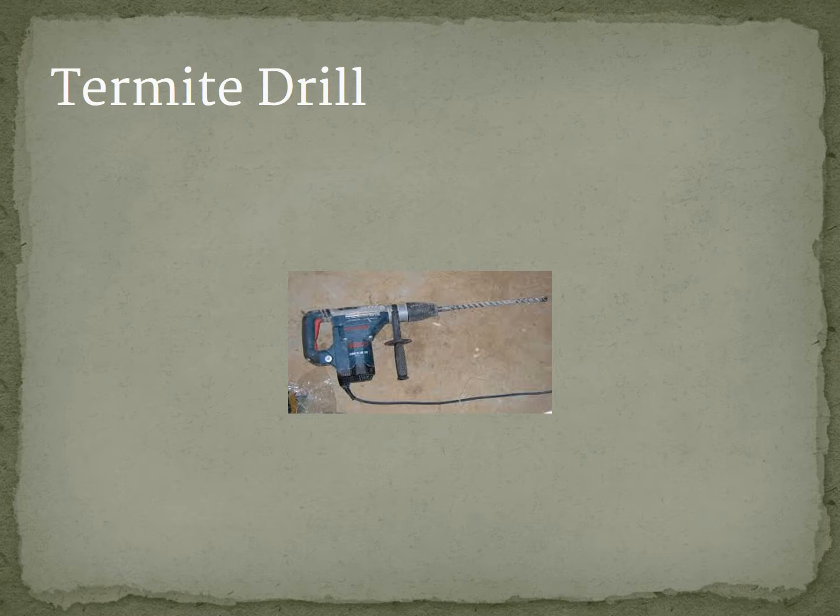I would suggest also as well that you keep sharp bits and extra bits on your trucks, because let's face the facts, you're drilling into masonry and concrete. You're going to have days where you do a ton of drilling and you're going to wear down the bits. So I would always keep extra bits on the truck, and a lot of times it would behoove you to keep an extra drill as well, because when we're out there treating, how often is it that we'll send two guys out on a job instead of one? And if that second drill was there, it'd be a whole lot easier for them both to stay busy.